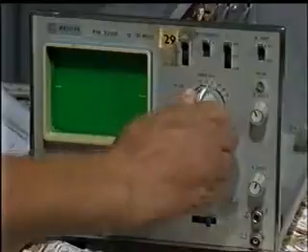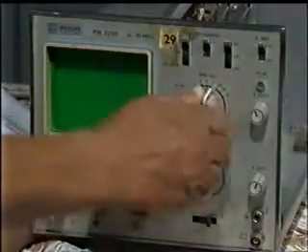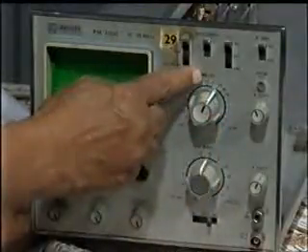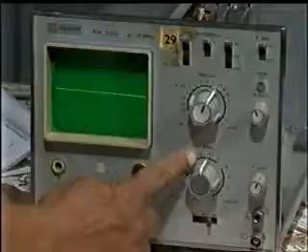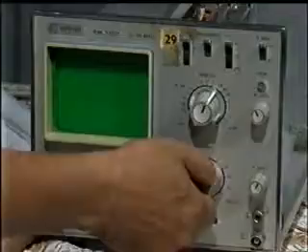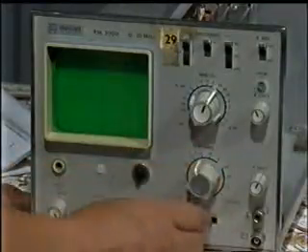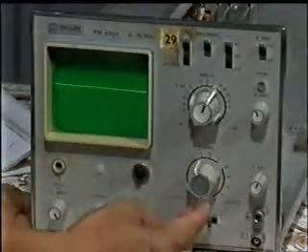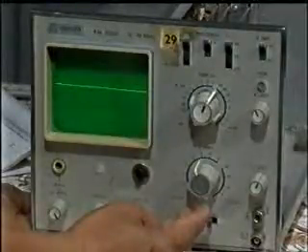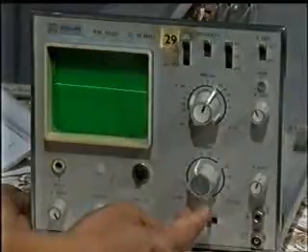If there is any problem in a junction or contact either in the time division switch or in the Y amplifier stage, it means the problem is either of the contact or some broken wire from the back side. And one should understand how to analyze these faults. In a similar way, one can detect the problem in the triggering stage.